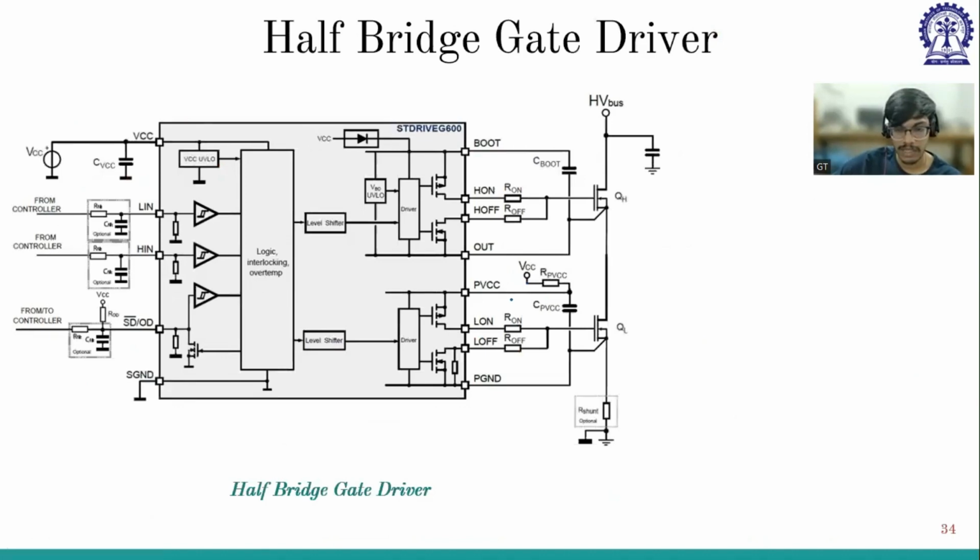And as I have discussed, whatever Q signal that we are getting will not be able to turn on the MOSFET, because the MOSFET needs a certain amount of voltage and a certain amount of current, and only then will it turn on. The Q signal cannot provide that current. That's why we need this gate driver, which provides sufficient current so that the MOSFET will be turned on.